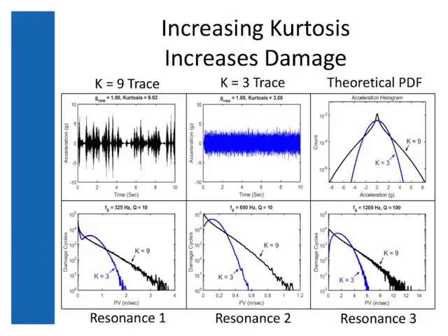Now for you math types out there, I know that a multi-Gaussian fit is not an orthogonal basis, and there are other ways to do this, but just for the sake of example, I'm going to pick Gaussian levels that are 0.25 GRMS apart, so a quarter of the test level, and just see if I could reproduce that histogram.